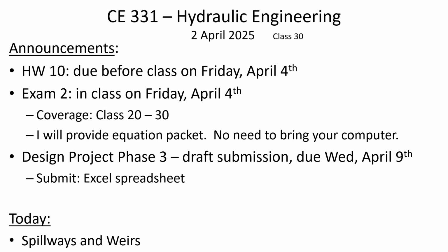The assumption being that you start off with an empty reservoir, you look at the difference between the inflow and the outflow for every hour, and then you say, during this hour, how much came in, how much went out, how does that compare to the last hour, like how much was already in the reservoir at a given time, so is the water level going up, going down? So that procedure just basically identifies the maximum volume that needs to be stored. So you've got that due Wednesday of next week.